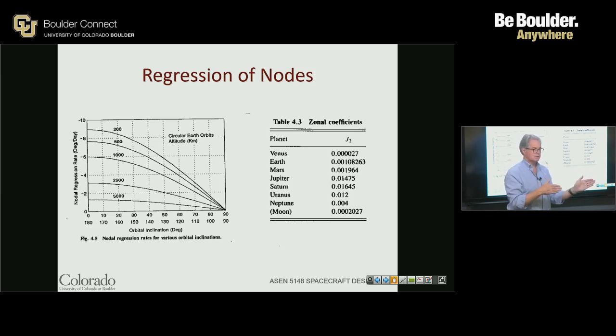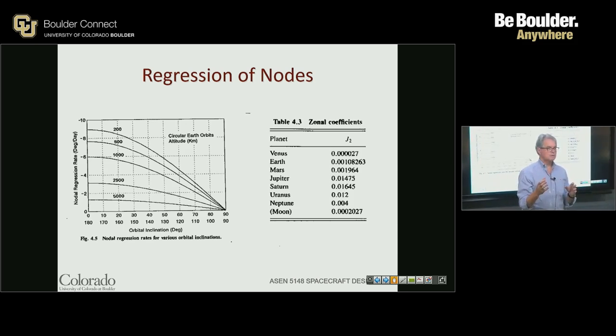This we call a sun-synchronous orbit, which is quite useful for observing the Sun, for observing things on the surface of the Earth. So, in summary, today we've talked about different types of orbits, what they look like, how to calculate velocity change. We've related that to interplanetary design through the Hohmann transfer. We've talked about two things that happen around planets with the orbits themselves. One is orbital plane motion in the plane of the orbit. The other is essentially taking that orbital plane and walking it around as a result of moving the angular momentum vector. Any questions for today?